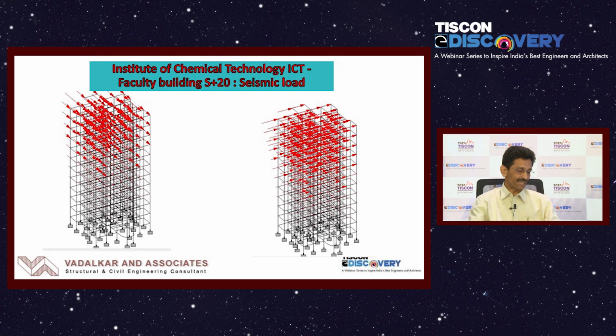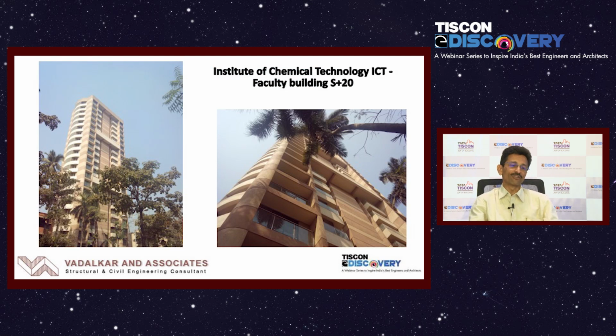Again, you have to apply the force in the orthogonal direction, in the x direction and in the z direction in the analysis, and then design the structure for this. This is the completed view of the building, a 20-story structure, and this is a close-up view. This is a very good building with all the shear walls inside.